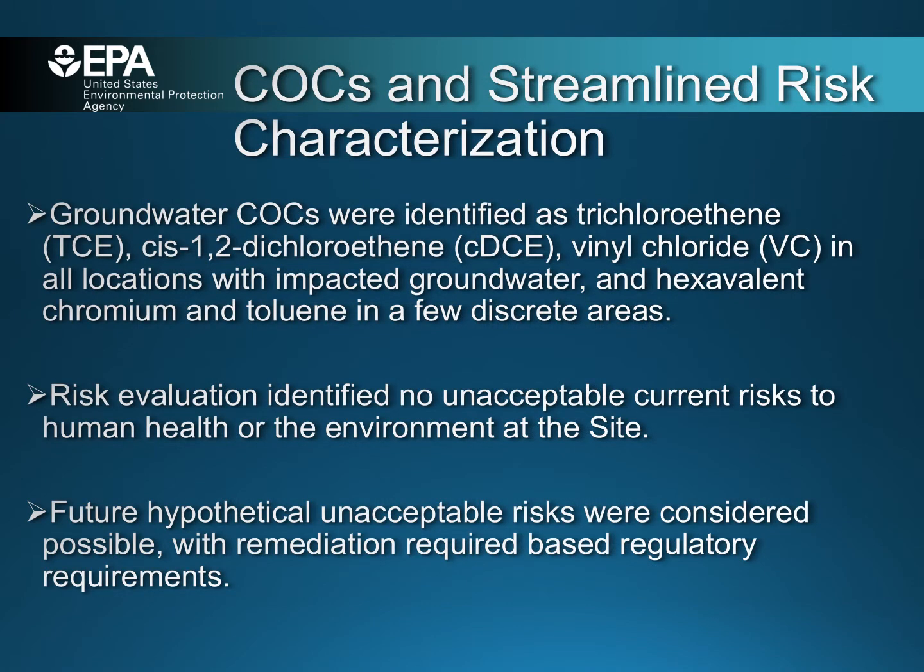Superfund is a risk-driven program. If there's an unacceptable risk, cleanup is warranted at a site. The study area was found to have concentrations that exceeded health-based risk levels, also known as MCLs, of trichloroethene, cis-1,2-dichloroethene, and vinyl chloride in all locations with impacted groundwater, and hexavalent chromium and toluene in a few discrete areas at the facility. There is no current unacceptable risk to groundwater because the groundwater is not currently being used.